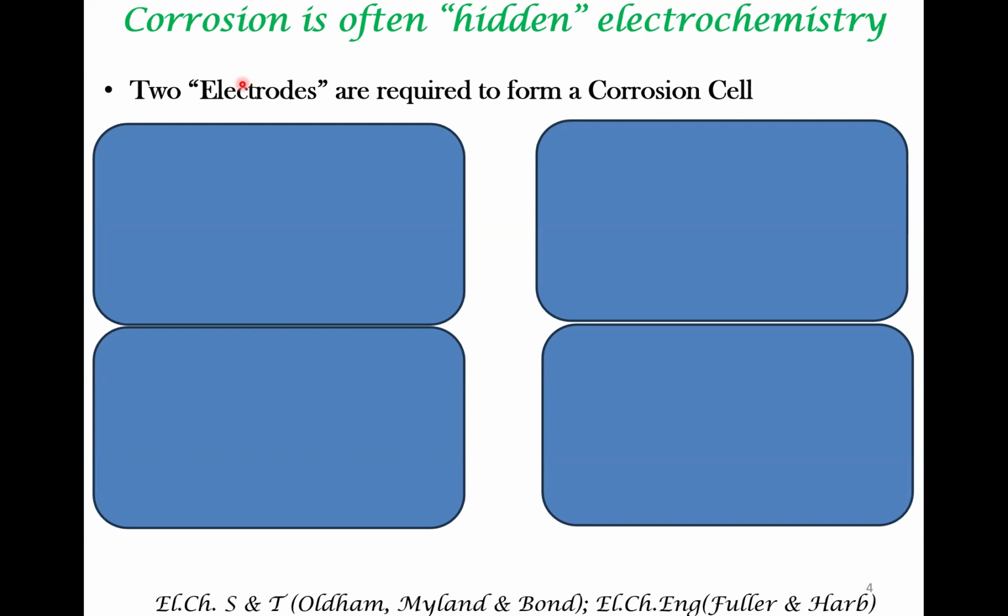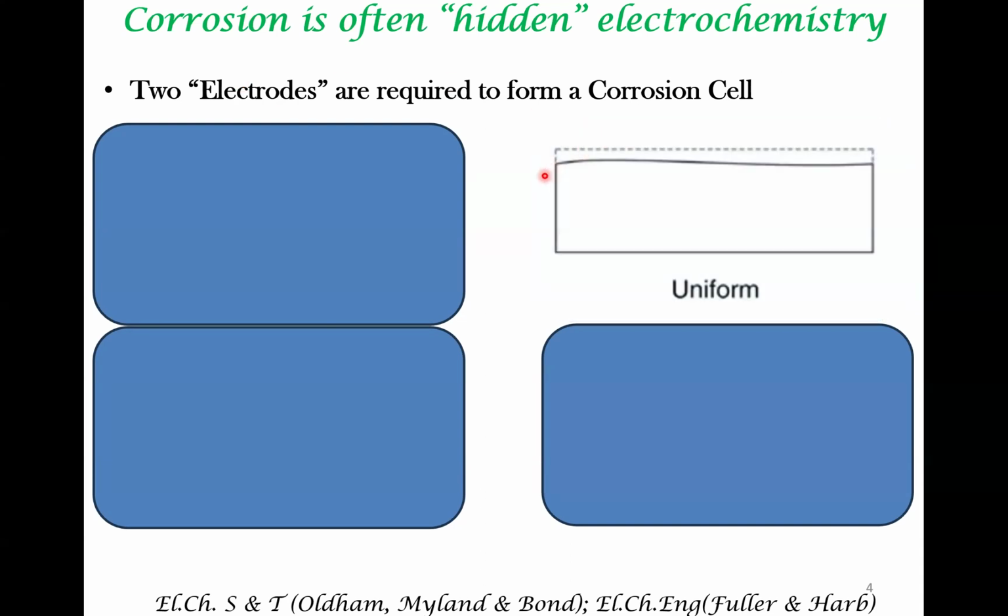Okay, so that is the typical electrochemical condition which you have often seen. But however, in the case of corrosion, this might not often be the case. For example, in the case of what will be referred to as uniform or generalized corrosion, there is a surface which is getting corroded. Okay, there is no simple or obvious way to look at this material as having an anode or a cathode which is separated.